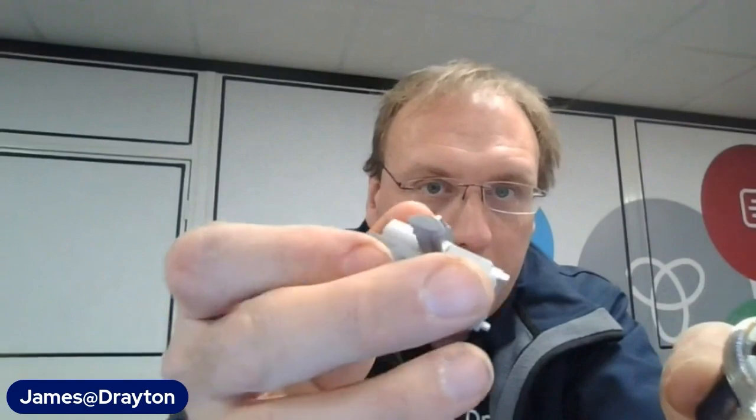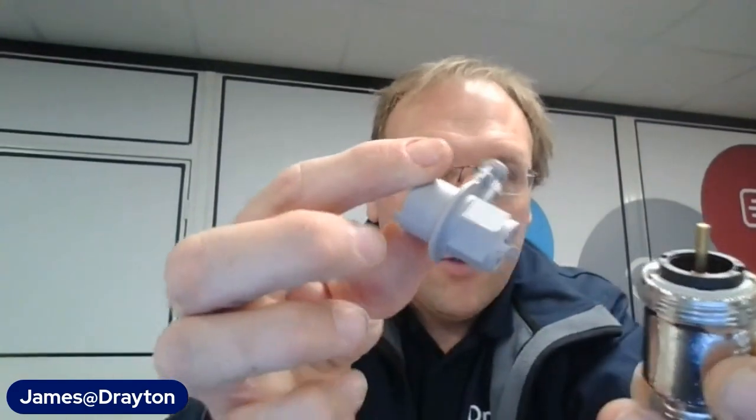Now, this key also has other features. So with this body, you can actually balance. Now, remember, the whole principle of balancing is that we're trying to increase the resistance of a particular radiator in order to make sure that there is no short circuit path through a radiator from the flow and return back to the boiler. So you want to be keeping your return temperature below dew point, so below 54 degrees, and that keeps your boiler in condensing mode. So the way we do that is, generally speaking, the radiators that are closer to the boiler will have more resistance than the ones further away.